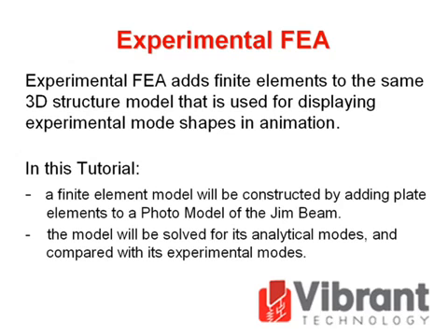Experimental FEA adds finite elements to the same 3D structure model that is used for displaying experimental mode shapes in animation. In this chapter, a finite element model will be constructed by adding plate elements to a photo model of the gym beam. This model will then be solved for its analytical modes, and they will be compared with its